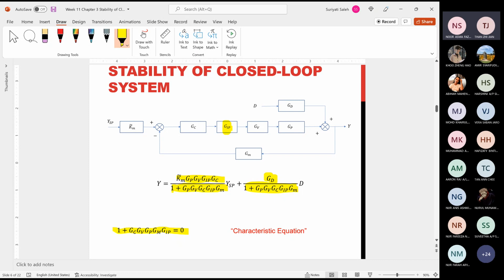Normally in our case, we just use two block diagrams to avoid further confusion. Either we use the standard or this one. So there will be two. How to know which one to be used? You take a look at whether they give the information about the transducer or not. No information about the transducer indicates that the standard block diagram will be used. If they mention the information of the transducer, you should use this kind of transfer function. So that is how to differentiate.